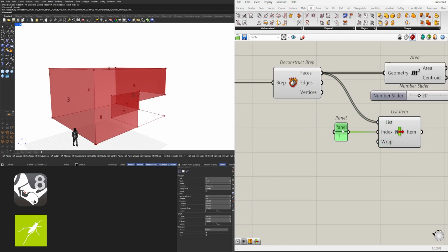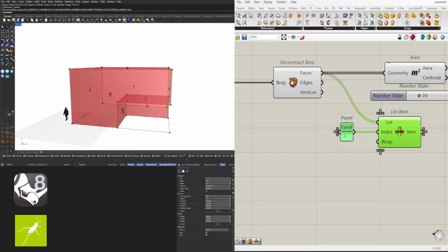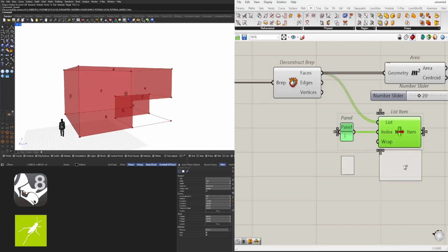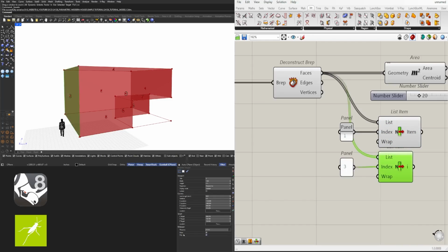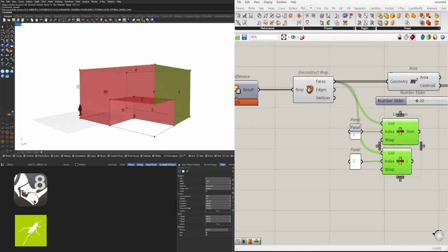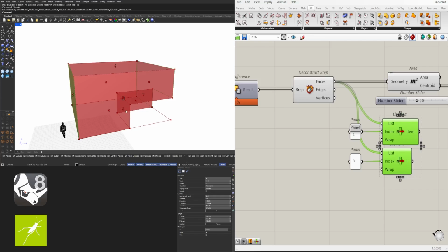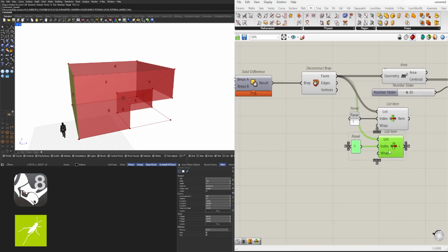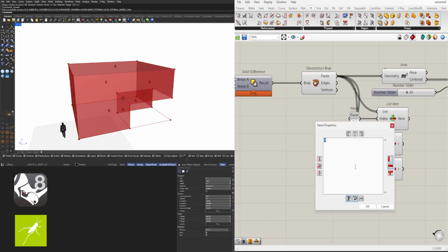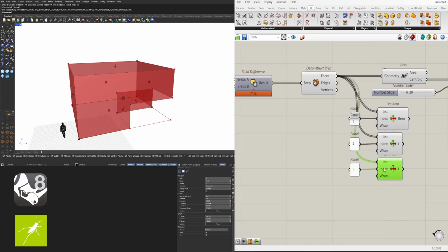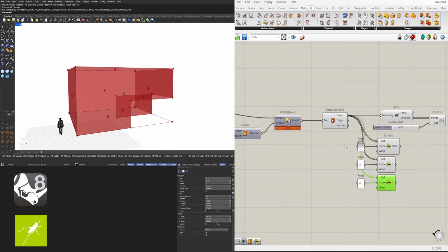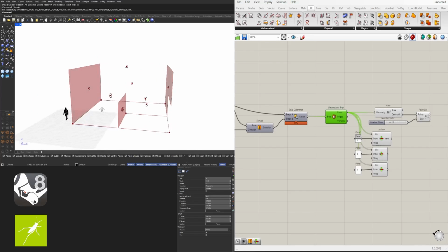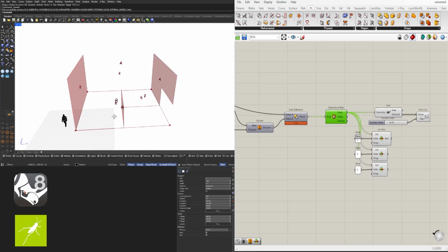So rather than using a slider, because the slider can change, and we know these are going to be consistent, I'll take this down, tap Alt, bring in the third one. So now we have both sides here. Now we're going to bring in the sixth one. This one, down, tap Alt, 6. And I can disable the preview on this just to see the faces that I'm extracting.